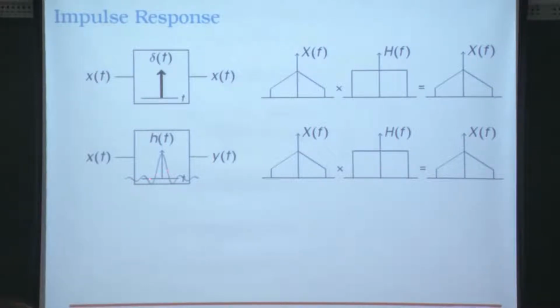Here it is an impulse, here is a sinc function, but both produce the same output. So the band limitedness plays a game here: the system is also effectively an impulse. This is a key modeling thing that we can use to simplify a lot of the models out there in wireless or wireline communications.